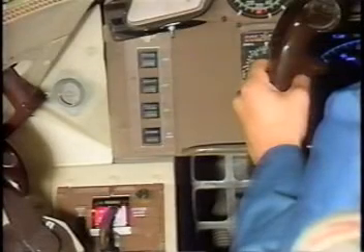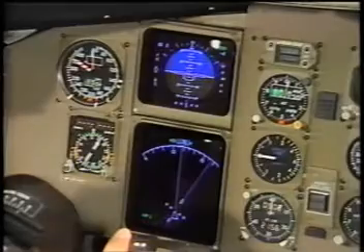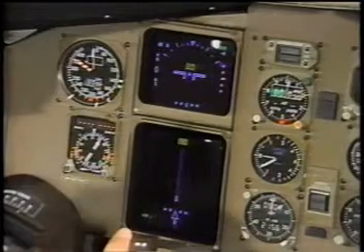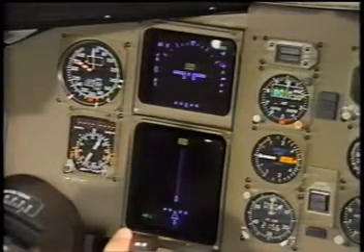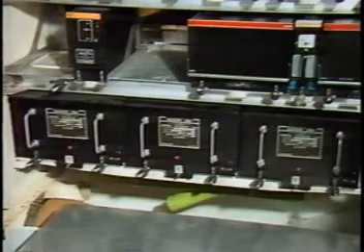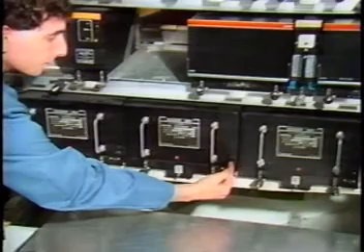To perform an interface test of the center IRU, press either the Captain's or First Officer's IRS alternate instrument source select switch. This causes the center IRU to display its test value outputs to either the Captain's or First Officer's EADI, EHSI, VSI, and RDMI. To start the test, press the center IRU's front panel interface test switch.